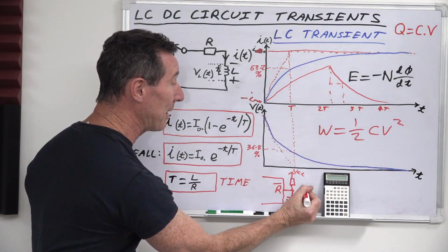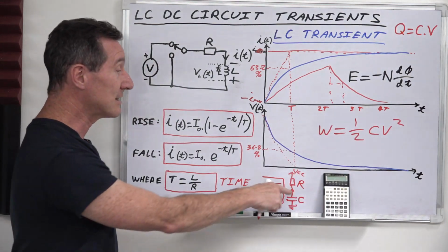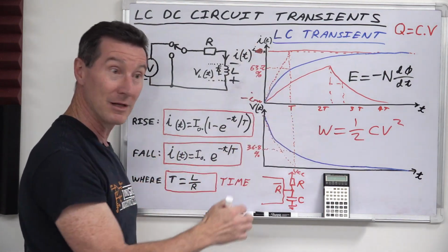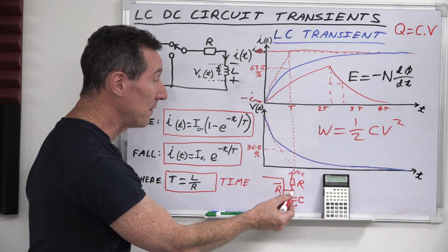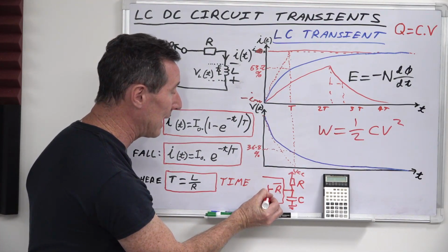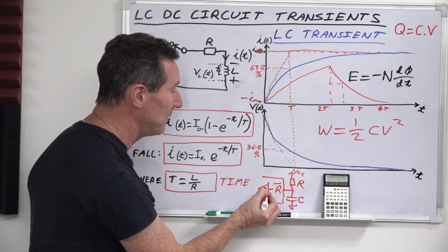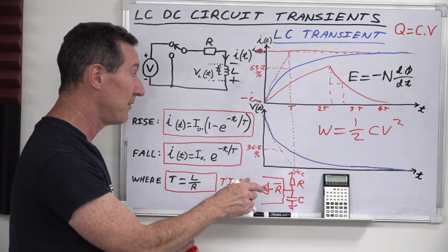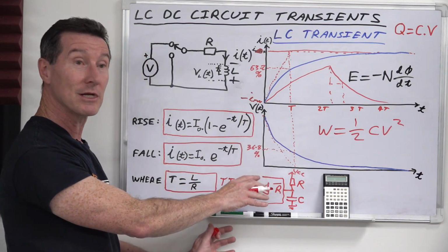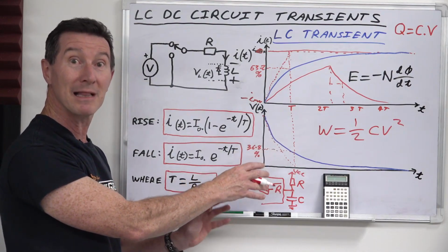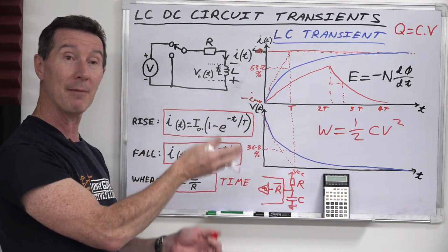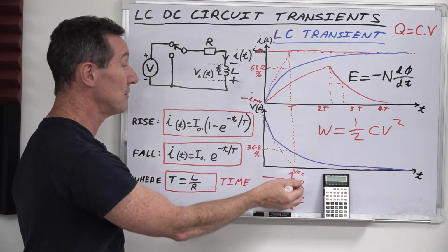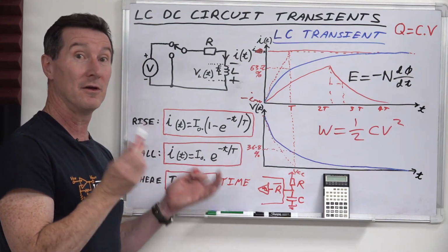Well, that's what you have a capacitor and a resistor for, like this. The capacitor will keep your reset pin low for the time constant, using the formulas that we've looked at, until the voltage on this pin reaches the threshold. This will be a Schmitt trigger, by the way, and I've done a video on Schmitt triggers because you don't want to use your regular gate in there. Anyway, I'll link the Schmitt trigger video if I remember, and then it'll hold the processor in reset for X milliseconds while the power supply rises up, and your processor's not going to do funny business. It's going to have a nice, clean start. So RC time constants for your digital stuff are used all the time.